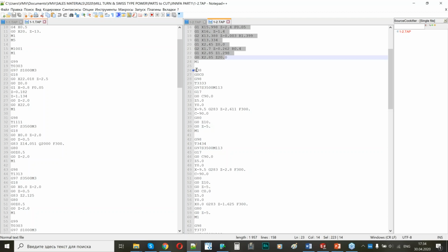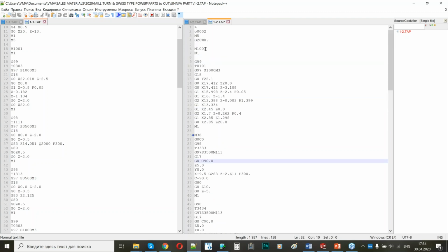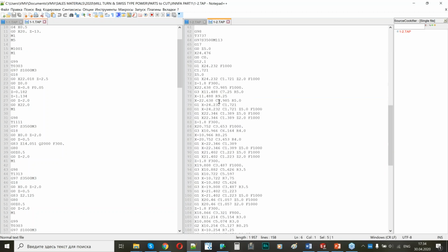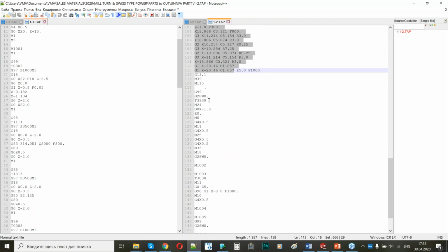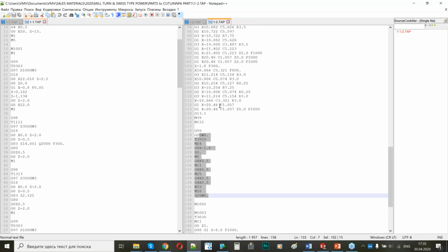This is the code for the C-axis on. So we position the C-axis. Whatever it looks like, it is similar to mill-turn machines, but signs may be reversed, and we need to remember about the wait marks. Here we have the operations on the back spindle up to the part catcher.